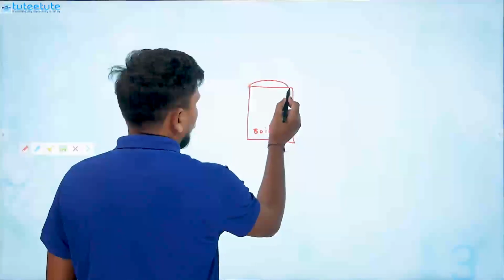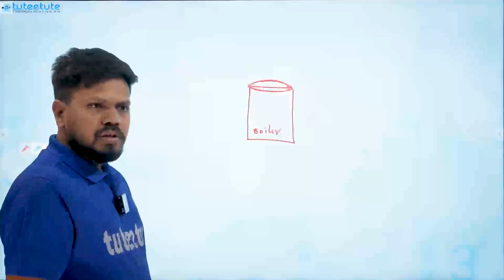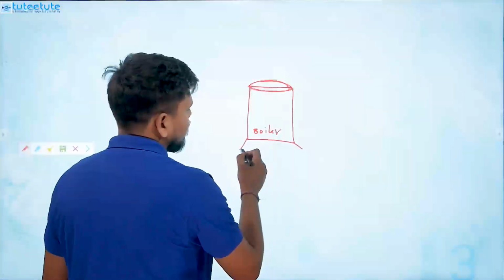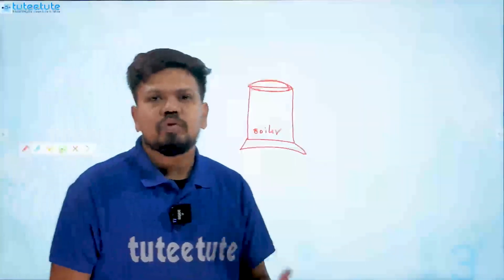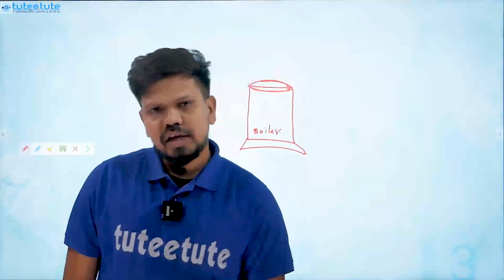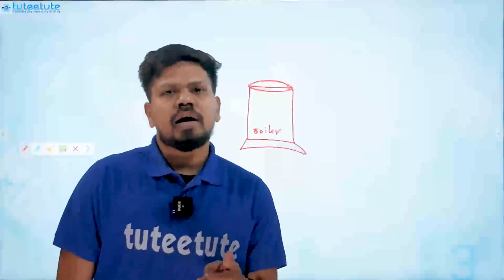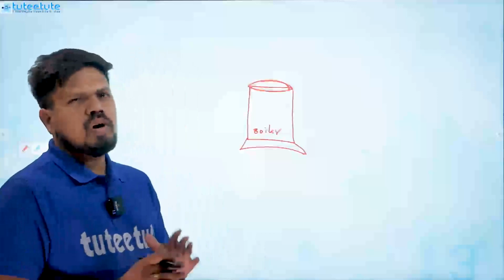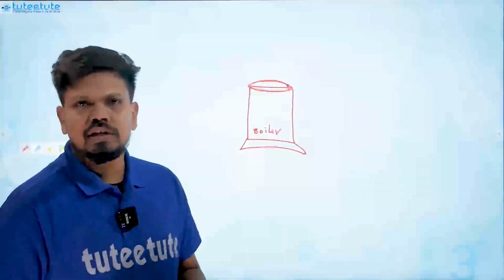That means the boiler has to burn inside. Burn means it has to combust inside. So how is it possible? We have to send some inputs to this boiler. Which inputs do you have to send? You have to send coal input, water input and some air input. Generally coal and water, these two are enough, but we will send air also. I will tell you why we have to send some air.